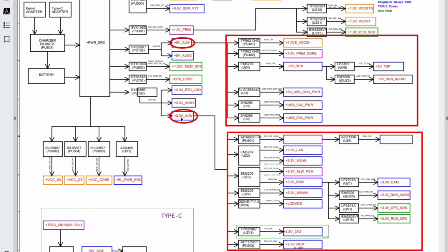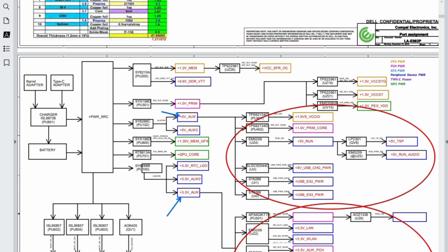Because we discussed this power sequence, let's see an overview of it. The first thing to check, of course, is the adapter. Here we have the adapter. Is the adapter good? You should check if the adapter generates 19 volts. Depending, of course, on the type of laptop, it could be 20 volt, 18 volt, 12 volt, etc. Let's assume the majority of laptops will have 19 volt. The first step is to check whether the adapter generates 19 volt.